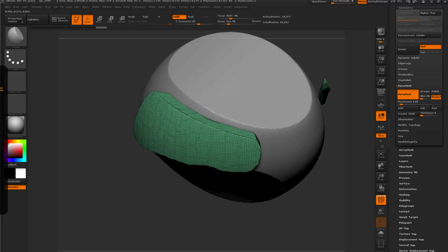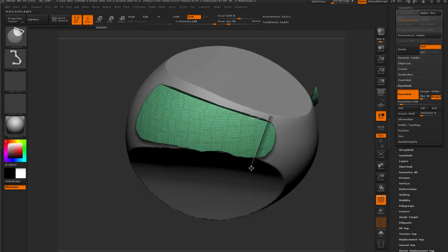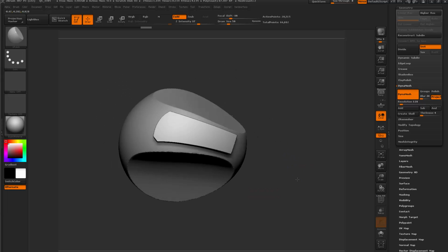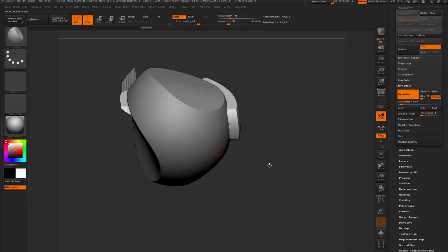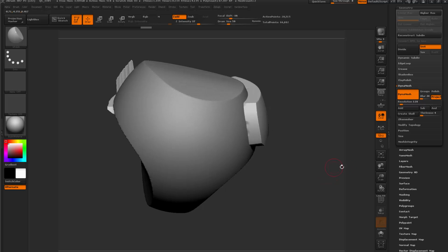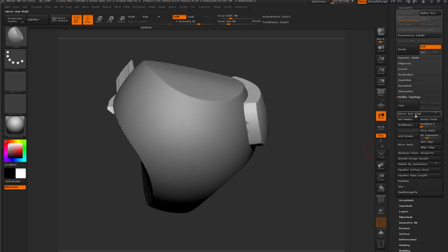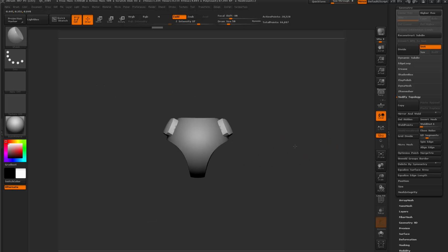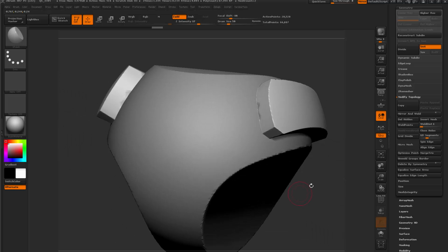And then I can clip it like that. So you see this workflow is all focusing on doing the shape and not worrying about topology. I forgot to turn on symmetry, so the other side is all destroyed. No big deal. I can go Modify Topology, Mirror and Weld to mirror my model to the other side once again.